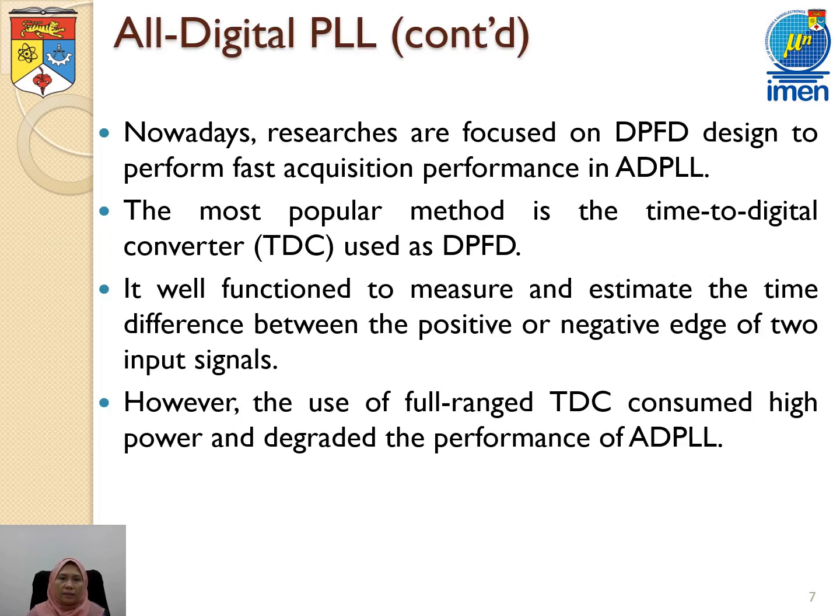So nowadays, researchers are focused on digital PFD designs that perform fast acquisition, and the most popular method is using the time to digital converter, or TDC. This TDC functions well to measure and estimate the time difference between the positive or negative edges of these 2 input signals. However, use of the full range of TDC will consume high power and degrade the performance of the ADPLL.